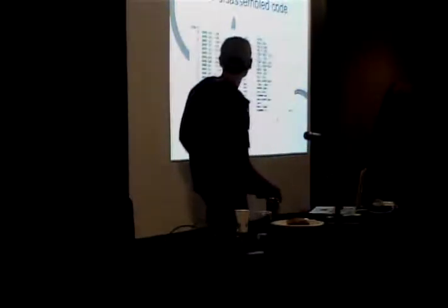And this is what you get. This is the disassembled code. So right here we have the memory address, the offset, and these are the actual hex. These are the opcodes, okay? This is actually the raw data. This is what all that crap was in hex, just the hex printouts, okay? And over here is the assembler. So these are your commands that are being executed, and they're pretty easy.